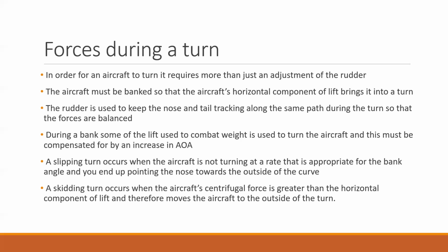There are two things that can happen if, for instance, you don't use your rudder pedals during a turn. These are called slipping and skidding turns. A slipping turn occurs when the aircraft is not turning at a rate that is appropriate for the bank angle, and you'll basically cause the nose to turn out towards the outside of the curve. This obviously is not desired, so you'll have to correct that nose pointing outwards with rudder to push it back towards the correct track of the turn.